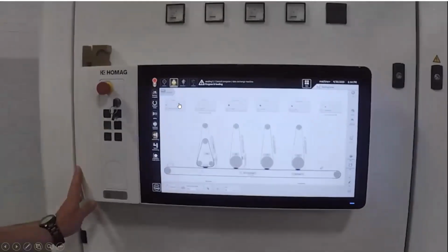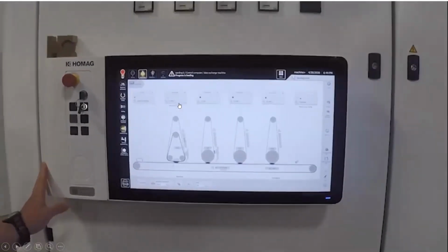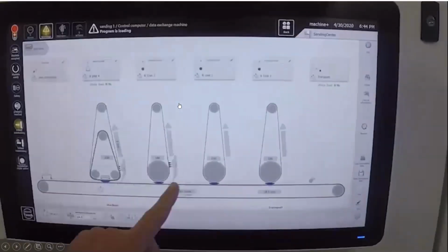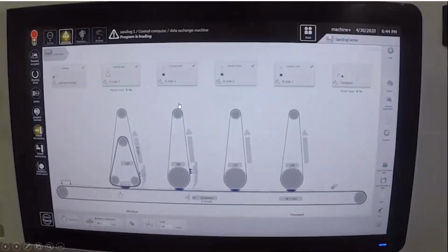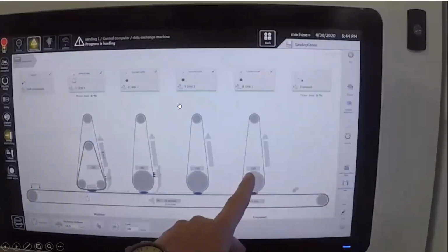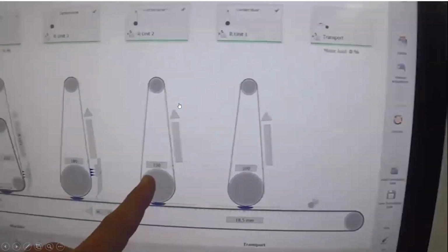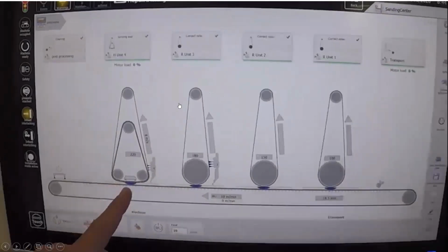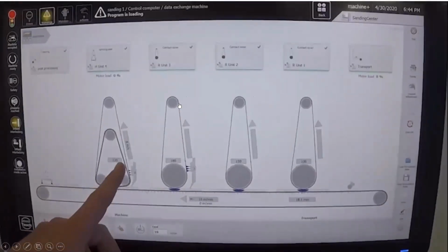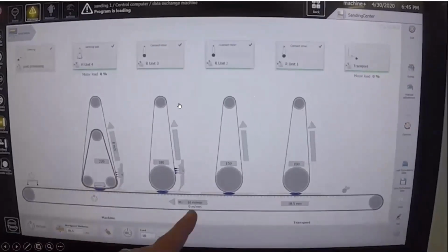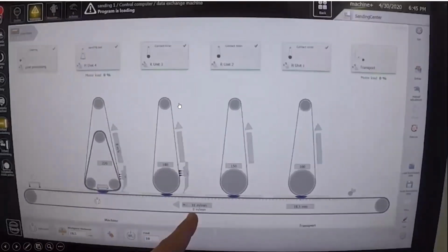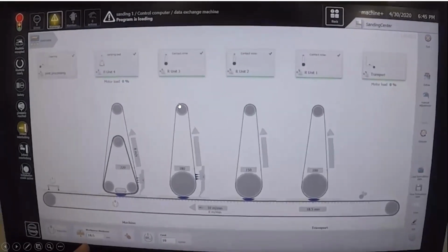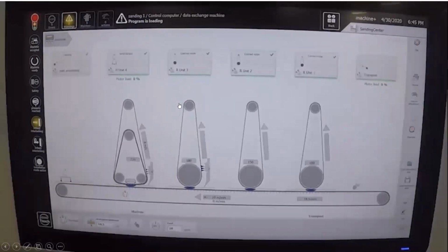So in this movie, this is on the HOMAG 345 RRRH, which means a drum pad. And as you can see, we're using a Power Touch control, and that's shared through a lot of the HOMAG family group of machines, such as CNC, edge banders, panel dividing saws, and in this case, the sander, as well as molders. So this is a very user-friendly interface. It shows all the information such as feed speed, the different grits on those heads. It gives you a diagram of each tool.